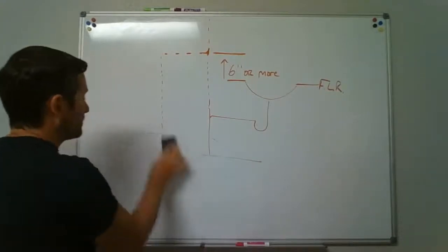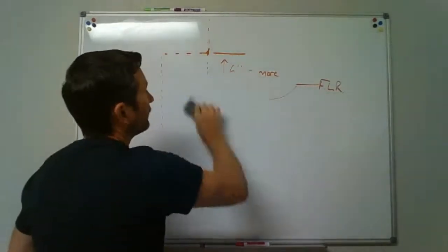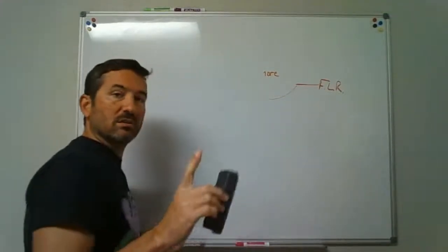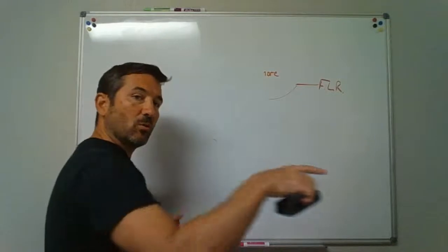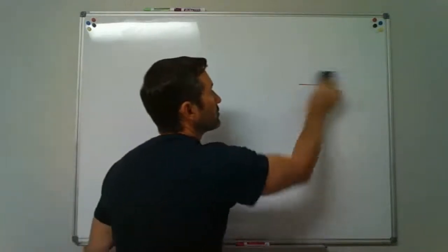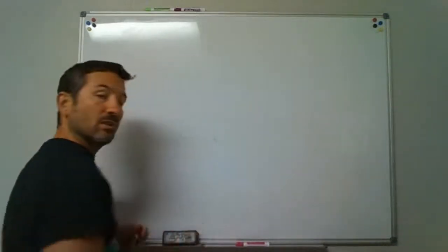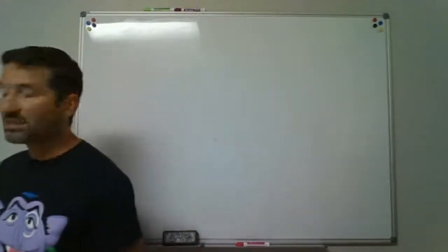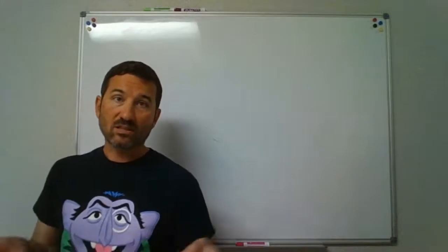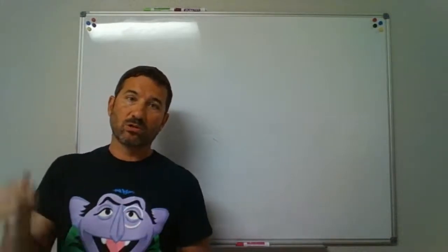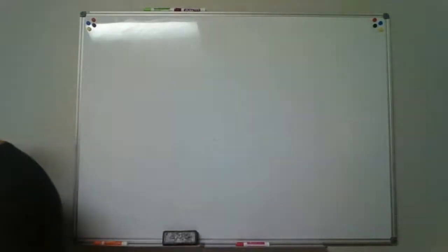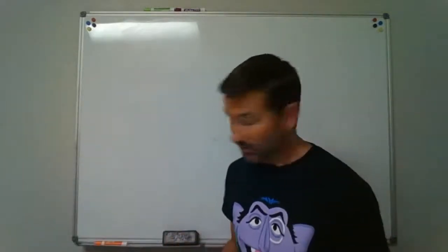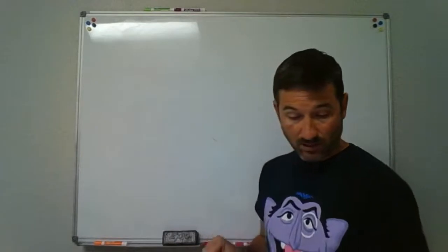It did have the exception saying remote floor drains, and saying, but why there's no way around it. Then it says, well, just take the vent coming up, rise 6 inches, run horizontal until you can get to a closest wall. Then go up with a vent, but you're going to have to throw a clean out on the vent. Just in case something gets clogged and that vent gets clogged, we need to be able to have a clean out so we can open that up and snake that out. Okay. What else do we have here?